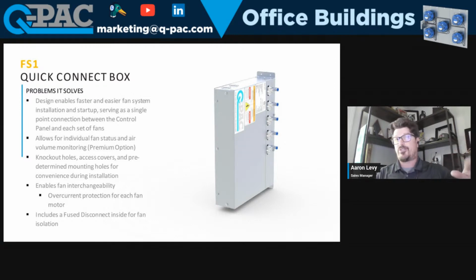There's a fuse disconnect circuit breaker inside there with mini fuses. That tends to be the biggest point of failure in there. That's what it's designed to do, to catch anything before it gets to the fans. So typically, if you do get a fan alarm, normally what I tell people is to check the fuses inside that disconnect as the first step. Normally we'll ship some fuses along with it, because it's very common if you get a high voltage spike or some kind of load change, maybe dirty power, that can take those fuses out relatively easily. But that's what it's designed to do. It's easy to replace a $5 fuse in a multiple $1,000 fan.